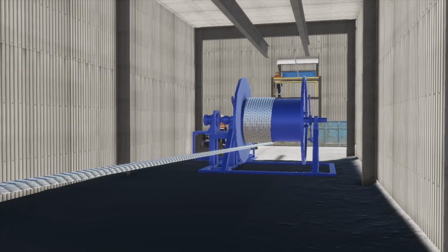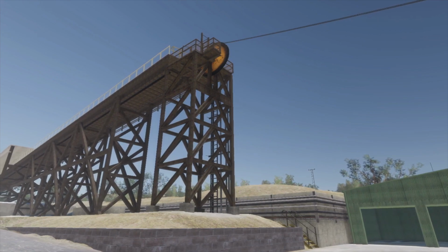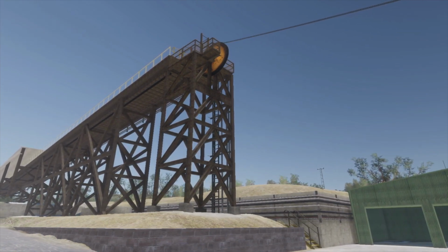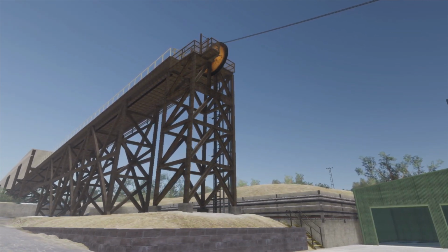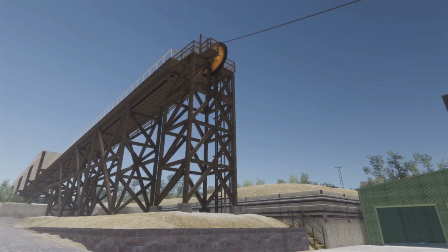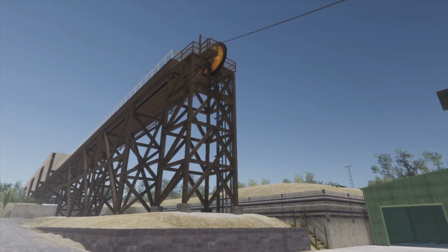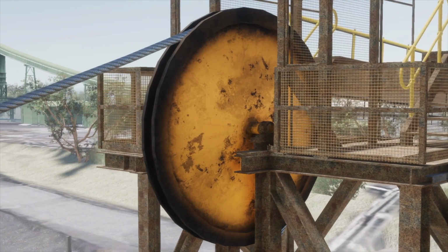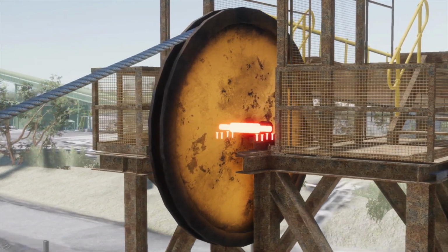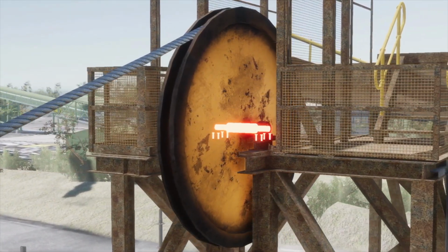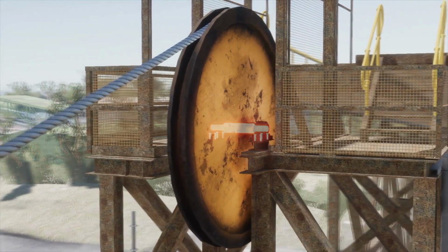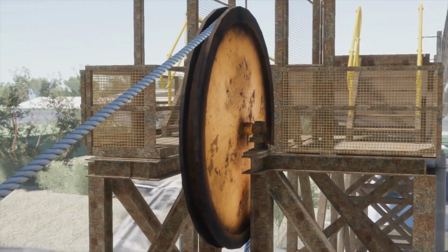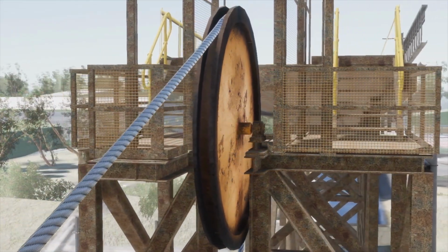Prior to the incident, a third-party engineering report was obtained, assessing the structural integrity of the head sheave tower and assembly. The report assessed a proposed 12-ton rope load based on the methodology drawing provided by the contractor. It found the head sheave shaft and hold-down bolts were non-compliant with relevant Australian standards and recommended an 8-ton rope load limit and that the hold-down bolts be replaced.